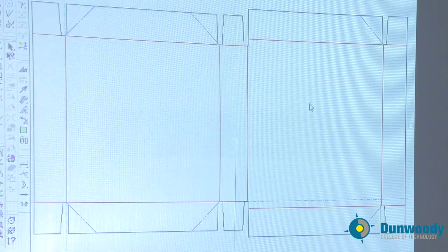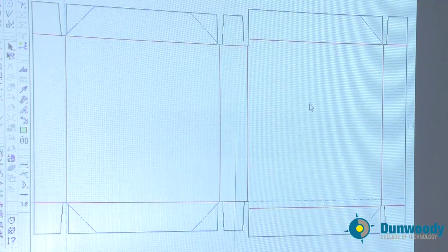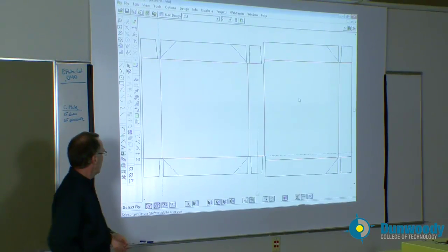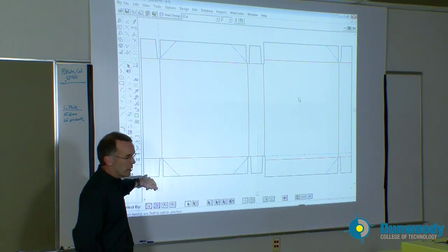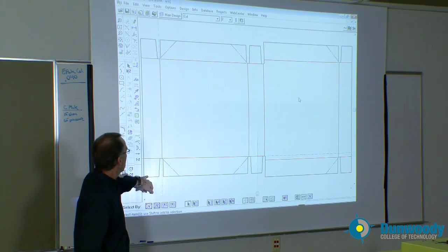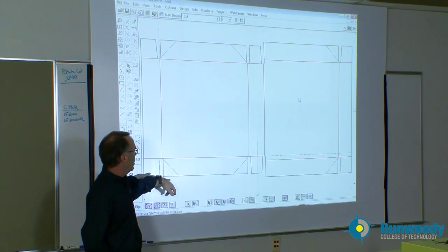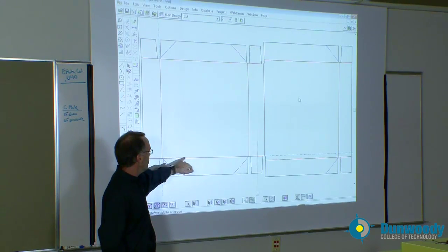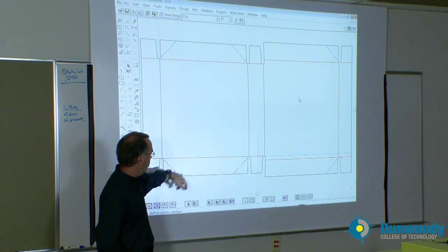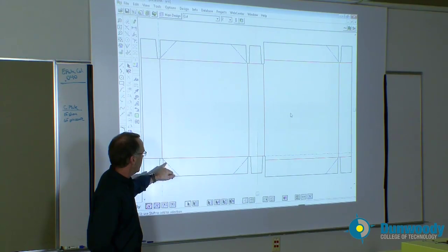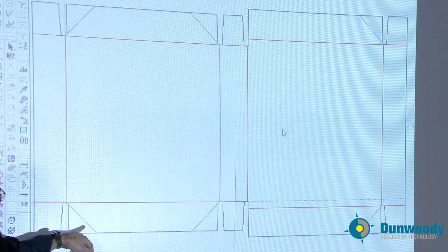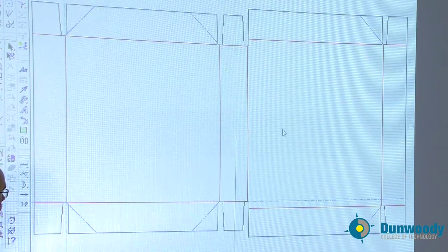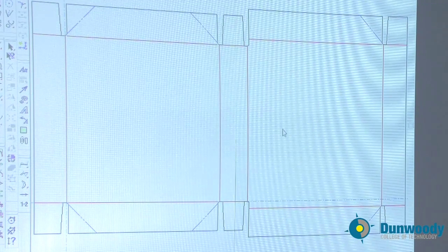So what Nate now has here is a flat die line. Again, the solid black lines here indicate the cut areas. And in this particular layout, the solid red lines indicate ordinary folds, and some of these blue lines indicate some more complex instructions, possibly a slit and score combination.